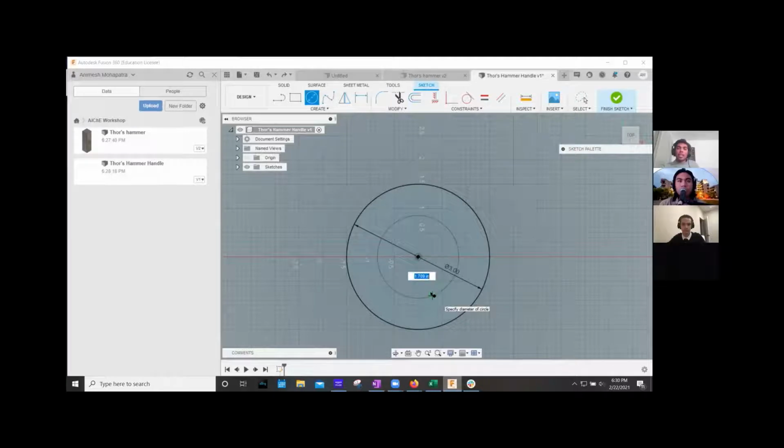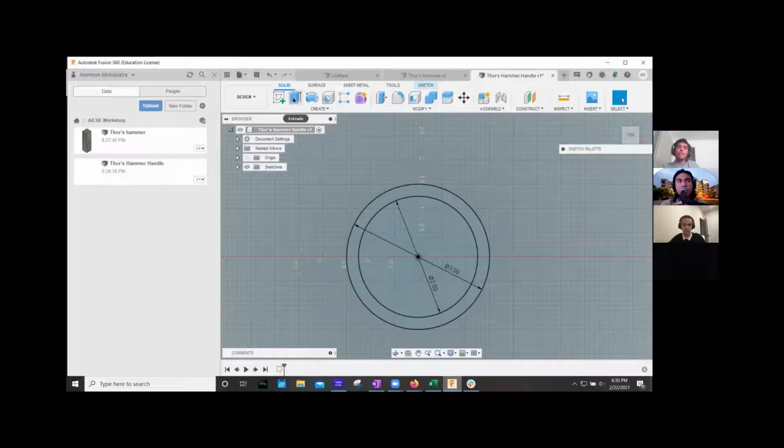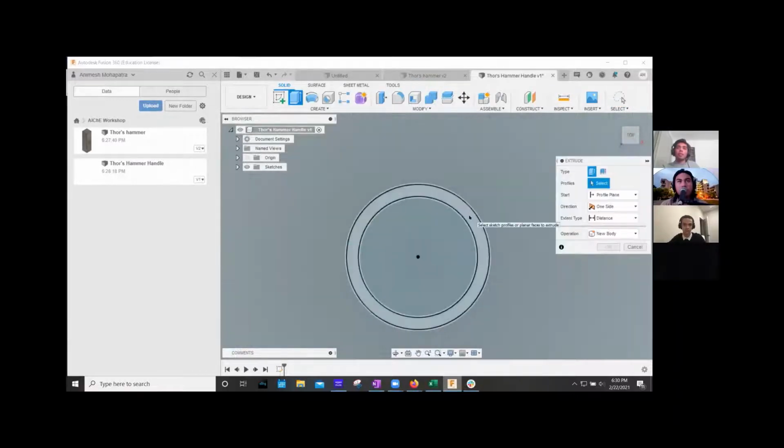And I'm going to say that the inside diameter is 2.5, because that just makes the numbers easy. So the inside diameter is 2.5, and the outside diameter is 3, which means that this wall, over here, should be 1/4 of an inch thick, and I'll show you guys how to measure that. But I'll show it to you once we've already made it 3D. So to make it 3D, we're again going to use the Extrude tool. So click on Solid, and then click on your Extrude tool.